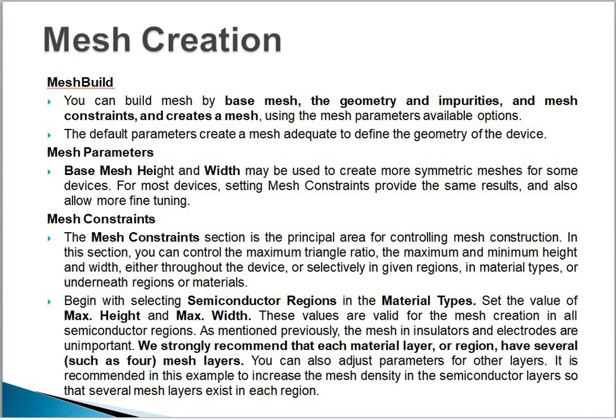Next is how to create a mesh in DevEdit. Mesh build. First point, you can build a mesh by base mesh, the geometry and impurities and mesh constraints, and create a mesh using the mesh parameter available options. The default parameters create a mesh adequate to define the geometry of the device.